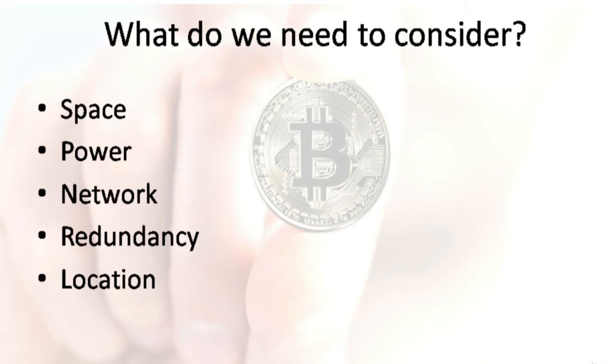The thing is that if you size it as stringent as possible, you might have cases where you have overload, or if you actually want to have some sort of changing of rigs that might require more power, you might overload your service, and you don't want that. So you should actually put a buffer to whatever that you estimate for your projected power consumption.